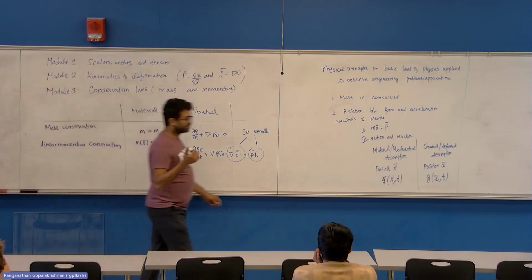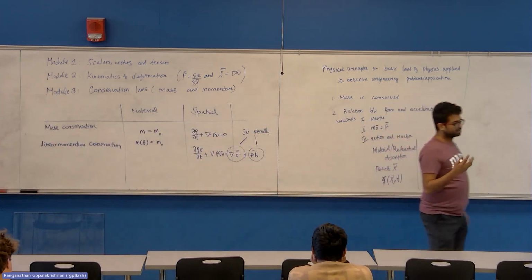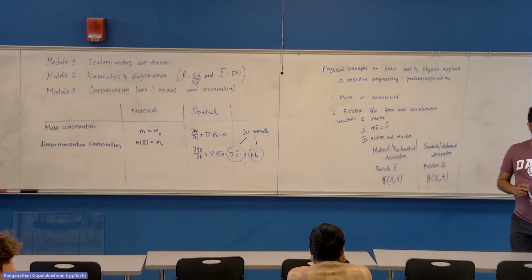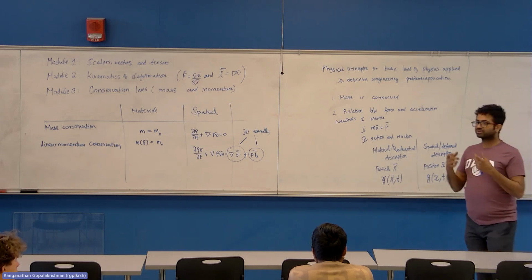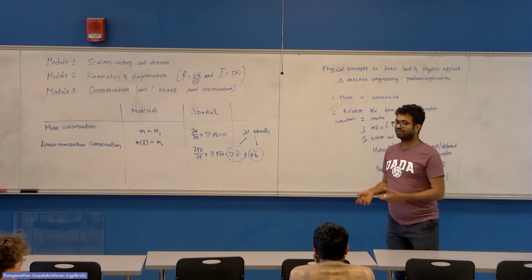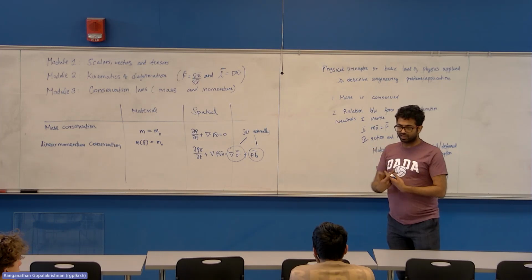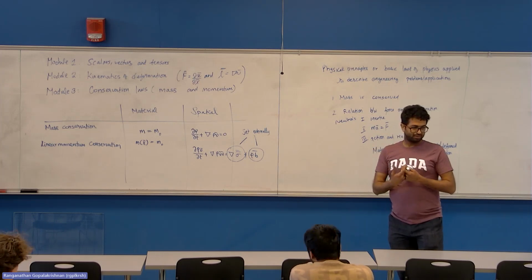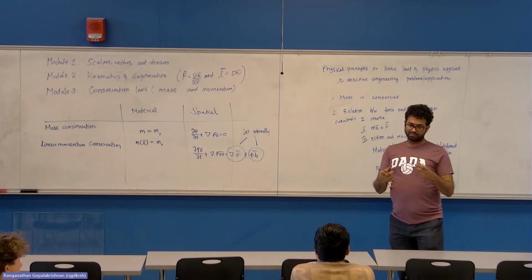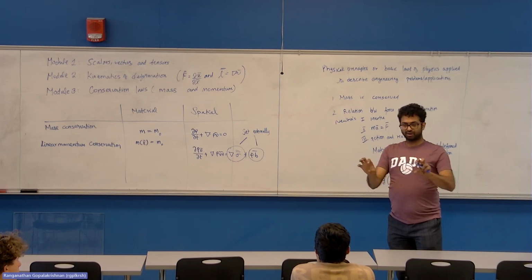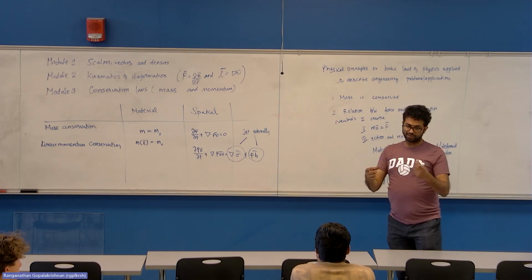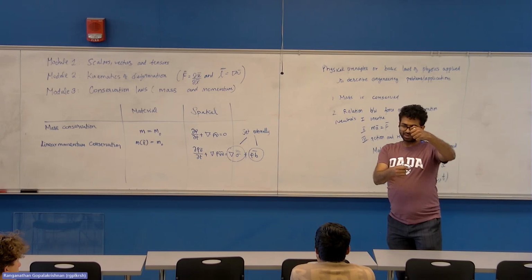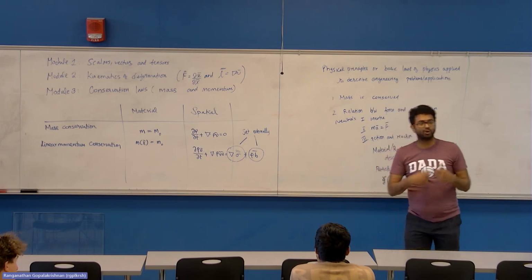When you are doing material testing, you tell me what is it? What is material testing? You make a sample. People who do material science like fracture mechanics or understanding how ceramics or polymers or composites or metals, if they are studying different types of materials, what is your protocol? First, you make a sample. It can be like a simple rod, or it can be a dog bone shaped piece that you put in a testing machine, and then you subject it to loading.